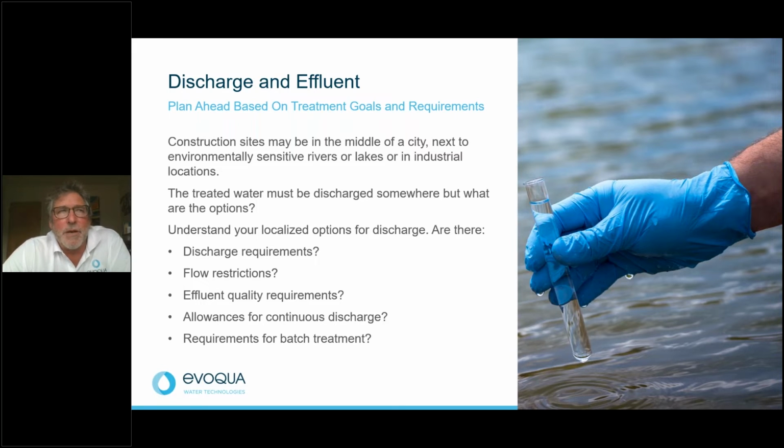Going to stormwater, because we're kind of the last line of defense for the discharge to the lake or stream or river, whatever. The criteria for discharge may be a little tighter, so you're going to have to get it down a little closer. And an NPDES permit, a stormwater discharge permit, just takes forever to get. In the state of Michigan, it may take you a month or two to get a permit. It's just the filing, the time to get it reviewed, it's frustrating. But if you're out of town and don't have access to sanitary, you've got to go to the stormwater route.